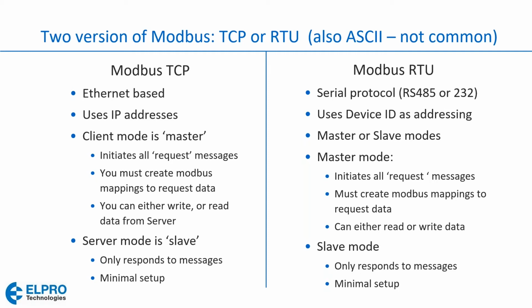However, there are some data rate limitations on that. Typically, you can get 4,000 feet if you use the lowest baud rates available. But if you start bumping the baud rate up to something like 115 kilobits per second, then the cable length is going to get quite a bit shorter than that 4,000 feet.